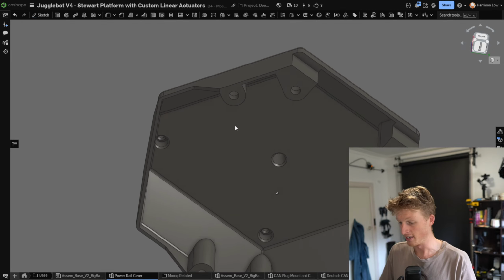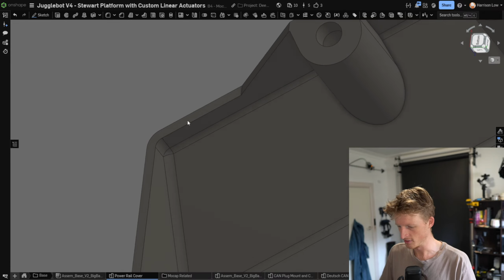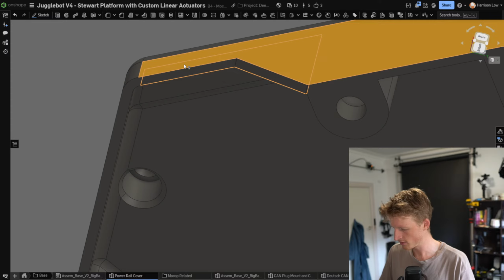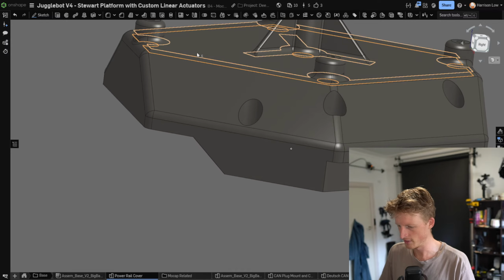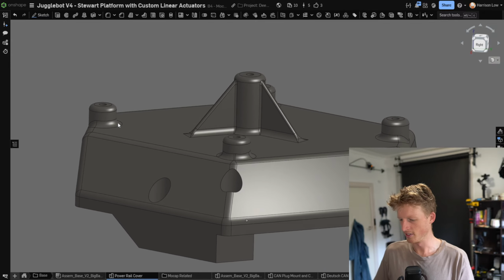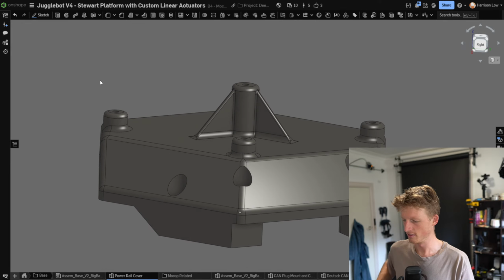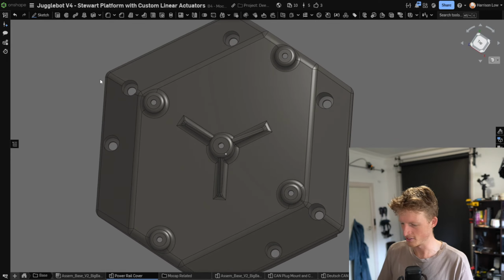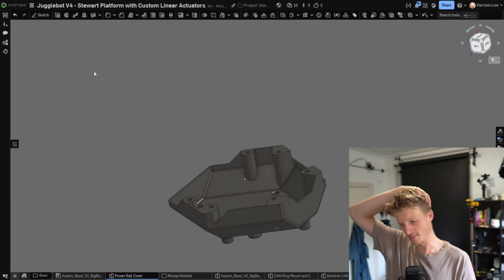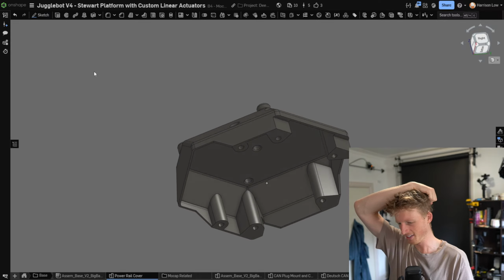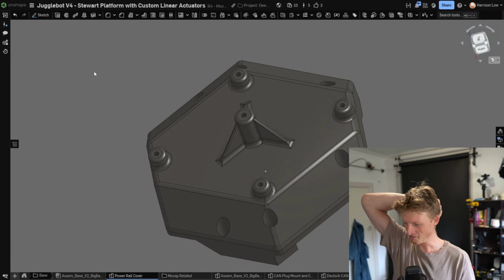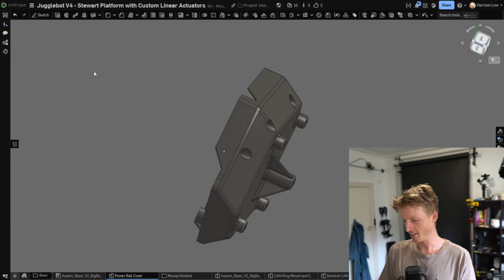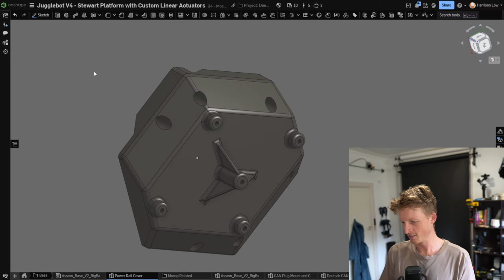They've suggested that if I increase the wall thickness, because right now it is kind of thin, about 2 mil I think the whole way around, to like 5, then it will have less chance of warping. But less chance is not no chance, and I kind of want no chance. So I asked about CNCing. They haven't replied to that. I feel like that would be a little bit expensive, but if they're sponsoring me then it doesn't really matter. If you guys have any thoughts on how to manufacture this, maybe I should just try 3D printing it with supports.